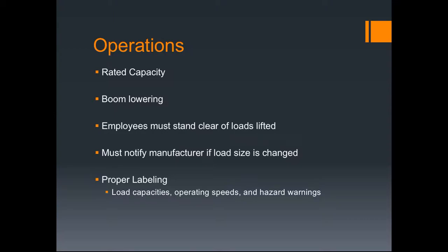And lastly, before you actually do operate a crane, a lift plan is essential, a lifting plan, so you know what the game plan is. A supervisor should also usually conduct a pre-lift brief to the team before operating a crane, just so everybody knows what is going on and what is expected from each crew member when a crane is in use.